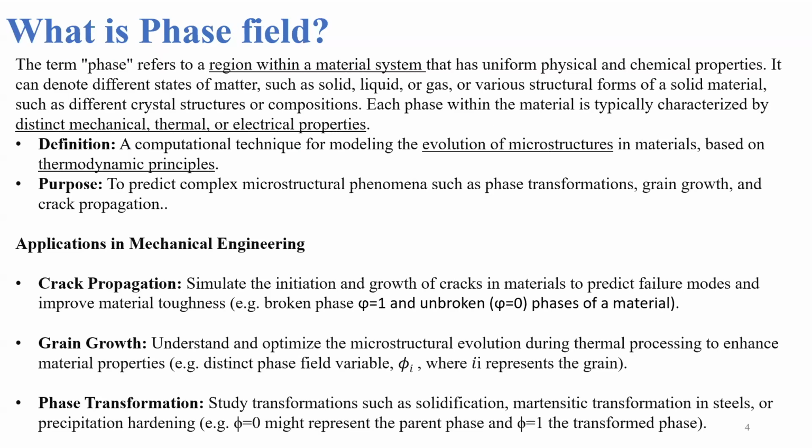So the term phase here refers to a region within a material system that has uniform physical and chemical properties. They are characterized by their distinct mechanical, thermal, and electrical properties. We will see this by an example very soon. A phase field is basically a computational technique for modeling the evolution of microstructures in a material based on thermodynamics principles. And we want to predict microstructural phenomena such as phase transformation, grain growth, and crack propagation.